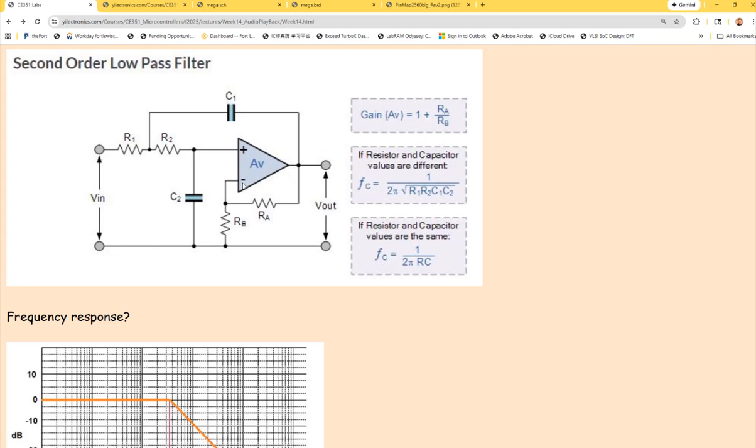So quick question for you guys. Is this a negative feedback or a positive feedback? You don't even need to think about it. All the amplifiers have to be negative feedback. It has to be negative feedback. So this is a non-inverting amplifier, but it doesn't matter whether it's inverting or non-inverting; there's just negative feedback over here. So you look at the negative feedback resistors to find out the voltage gain, right? So the voltage gain defines the DC gain.